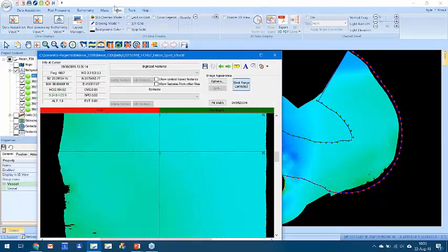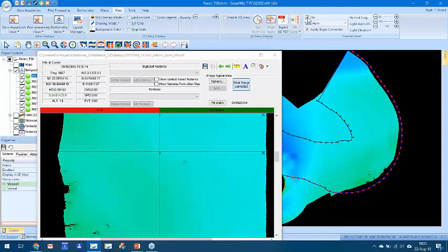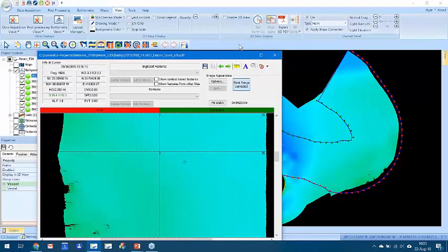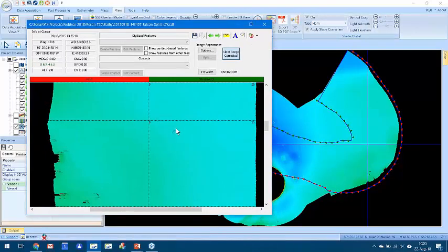To get that, you would go to the View menu and turn on the shaded relief functions, which have been moved to this View menu. So you turn them on here. There's a couple of different options. You can have slope corrections, you can control the vertical exaggeration, light azimuth, elevation direction. That's all dynamically done.